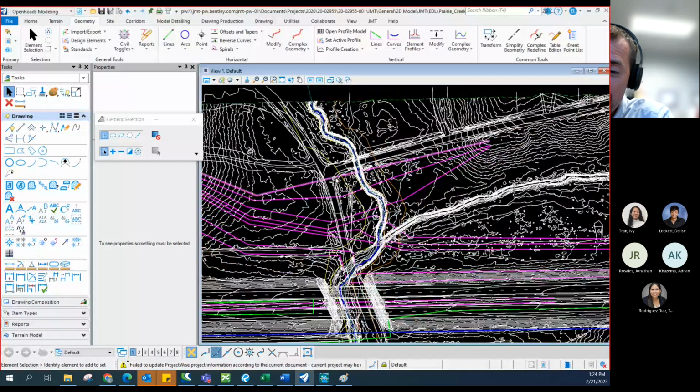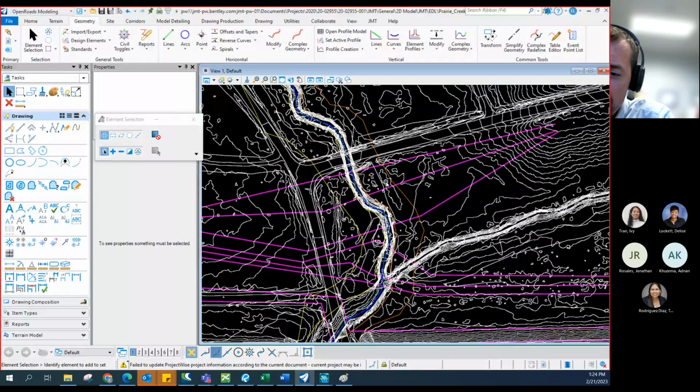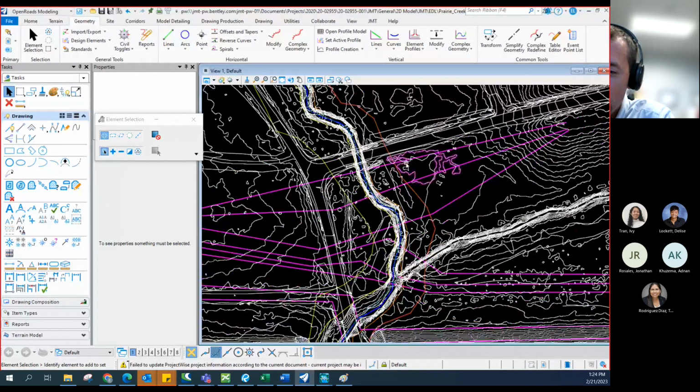That's going to be the exercise, where we'll build the model. When we drew in these flow path lines, we were trying to space them 1/3 of the way between the bank line and the edge of the cross section, or the bank line and the floodplain. Either one will get you close enough.